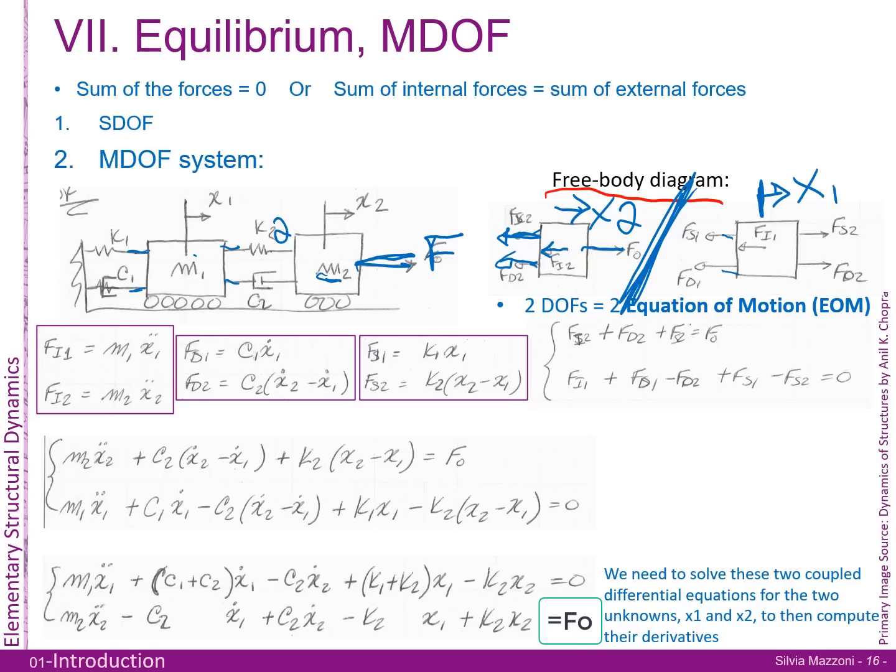Now let's look at our damping and resisting forces. Let's do the damping force here. Okay, actually let's look at the resisting force, because then the damping is the same. So the force here, K1, is equal to, because this is fixed here, the spring gets elongated along with x1. And it's very important to keep track of it: as x1 moves to the right, the force is going to be going to the left. And so we say Fs1 equals K1 times x1. And just by symmetry, that's the same thing for the damping force. Now let's look at force 2.